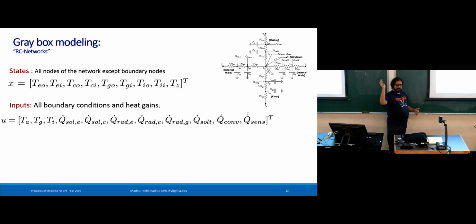We have transmitted solar. So some solar is coming through the window, directly getting added to the zone. We have convective heat gain from the occupants, let's say, and appliances. And then HVAC can be treated as this term that I had once introduced, sensible gain, because it's directly influencing the temperature of the air.